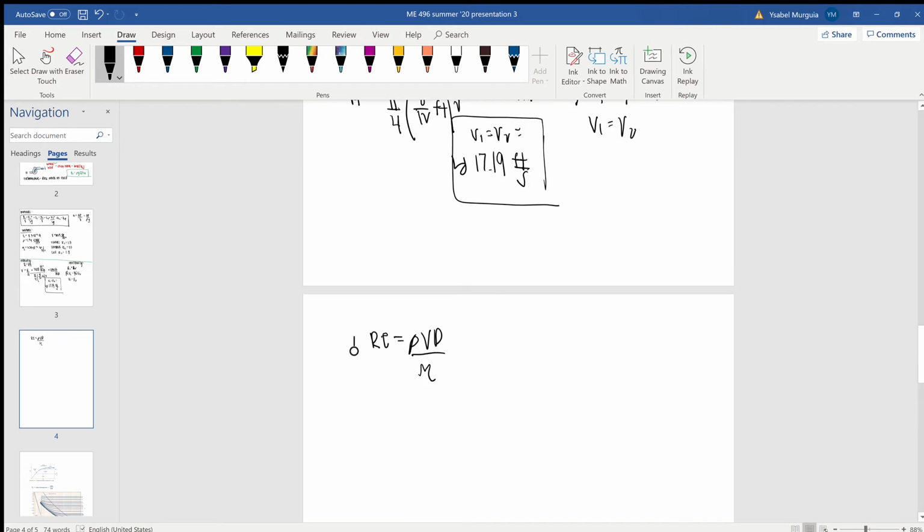Before I solve for it, there is one thing I forgot to define. The flow will be laminar if the Reynolds number is below 2100, or about 2000. And for purposes of this class it will be turbulent if it's above 2000, but it actually would be if it's above 4000, just because I'm eliminating the transitional flow.